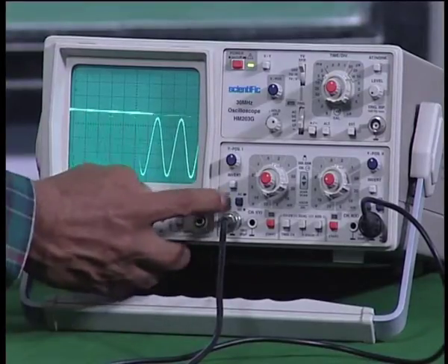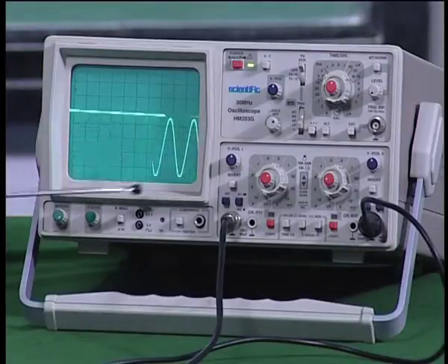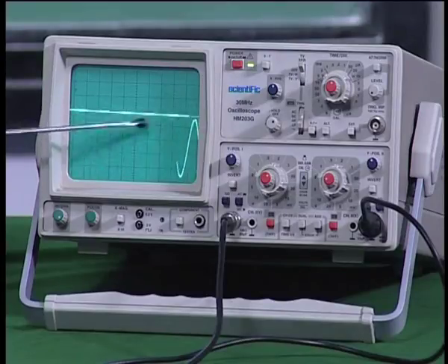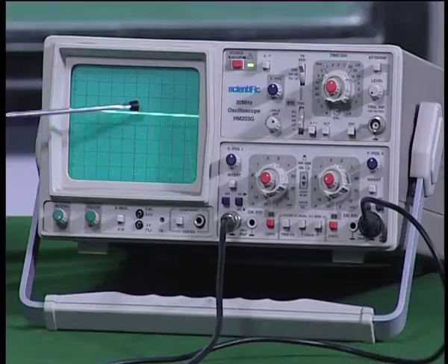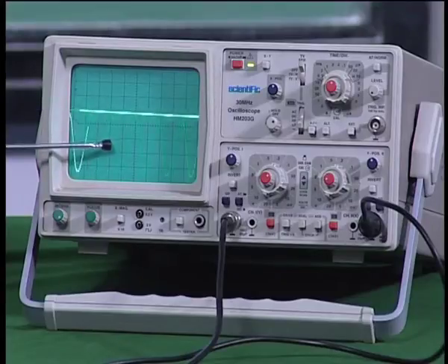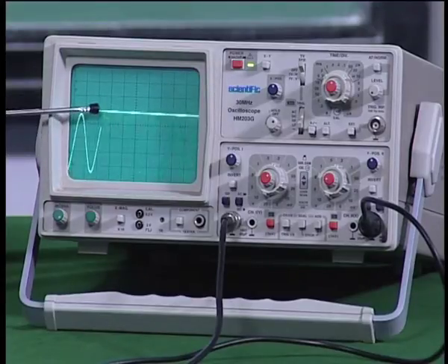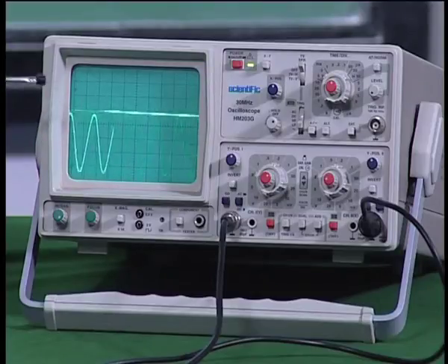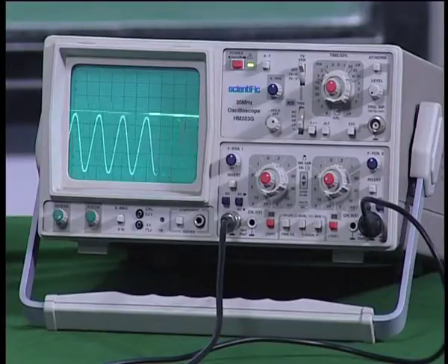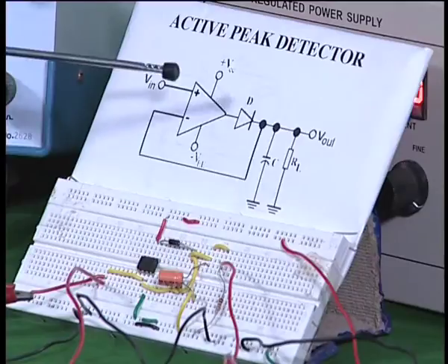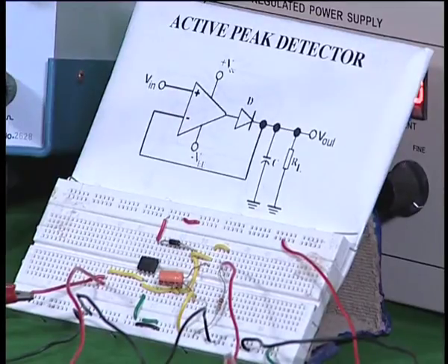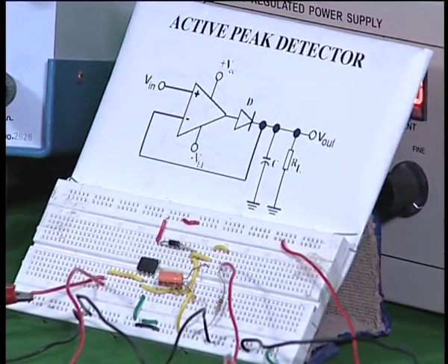So, instead of using a multimeter, I wanted to show you by using the DC coupling here that it goes from the 0 line to the peak value here, and this is the DC output that I get across the capacitor. So, the output is a DC, therefore, it looks like a straight line, but it is shifted with reference to the 0 line up to the peak value, and therefore, it is indeed a peak detector. I hope you understand that point. So, with a very simple op amp, diode and a capacitor, we are able to make a peak detector, and once I make a peak detector, I can connect it to a multimeter or whatever and calibrate it in terms of either RMS or peak voltage.